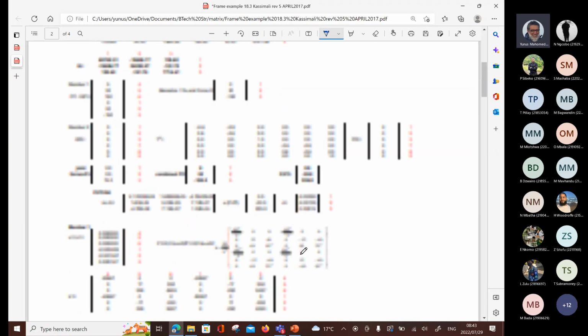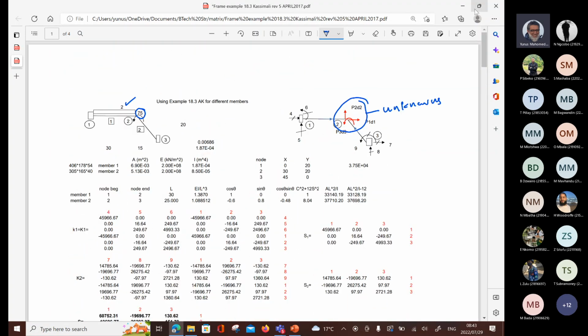This is something that is done at a little bit of a higher level, but we will see something very similar. We use a method called slope deflection, and in there we have to start by identifying the unknowns, and the unknowns are displacements. So we have 3 methods that we're going to use. Moment distribution, where we don't have to worry about displacements.